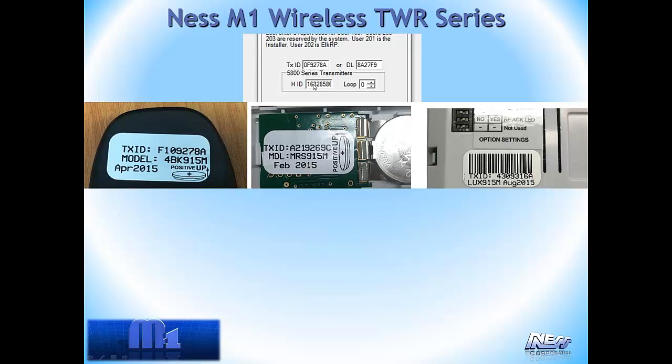The DL and HID numbers would automatically be entered as you're putting that number in. In this example, if it's a radio reed switch, again the first number, in this case an A, and then 9269C would get entered in there. First digit and the last 5 digits. And in this case the PIR, we put the first digit being a 4 and the last digits being 9316A. So that's how you just instantly look at the code there.